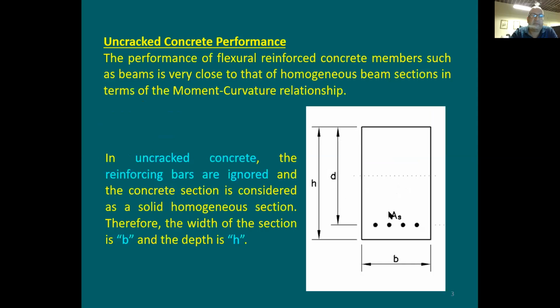This is the reason that you are going to be adding this reinforcing. Why? Because at a certain point, the crack is going to be growing, and what you would like to do here is to have these rebars resist the tension. It doesn't mean that the crack is going to stop, but it means that the rebar is going to start taking some tension force. The crack depth is going to be growing up to a certain point as long as you add loads. And also the reinforcing bar is going to be taking the tension force that you want it to take.